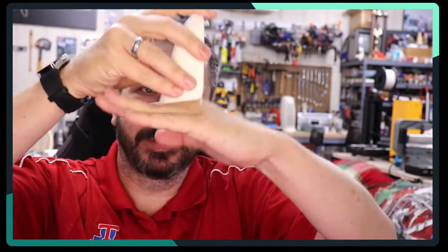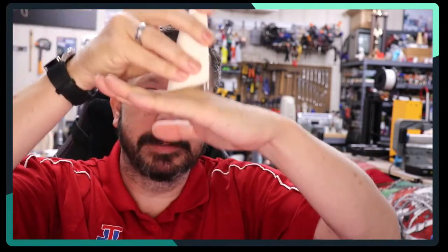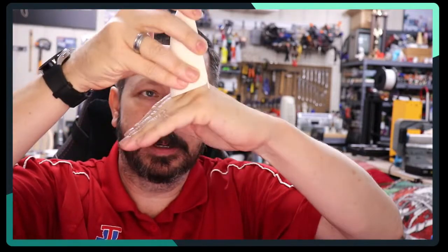And we're talking sub-millimeter level of deformation here, but it deforms upward, and then it gets to its set point and goes above it, and then the heater turns off and it deforms flat again, and back and forth and back and forth. And that little part you're printing is sitting on the bed, moving up and down, sub-millimeter, but still, it moves up and then down, up, down, and it creates those bands in the print itself.